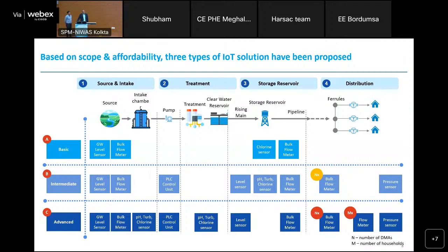Before the pumping, you need to have a water level indicator, because if the pump runs dry, it may go out of water, and that will be a huge, big problem. Secondly, at the treatment works also, rate of filtration is very, very important. So how and when to backwash the filter, that is another thing.